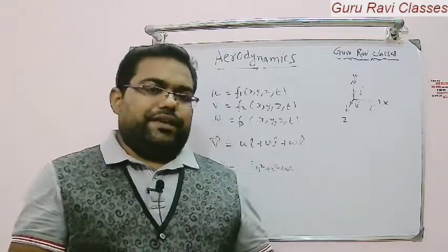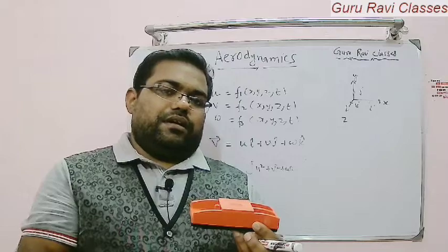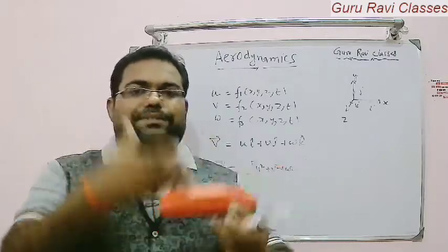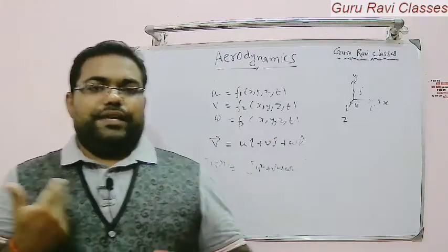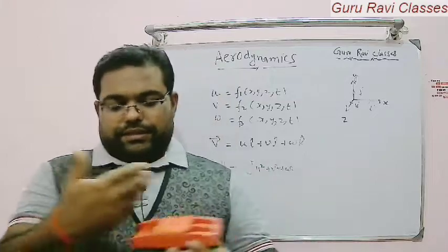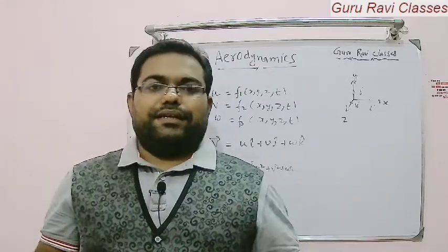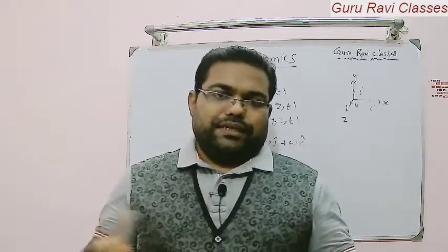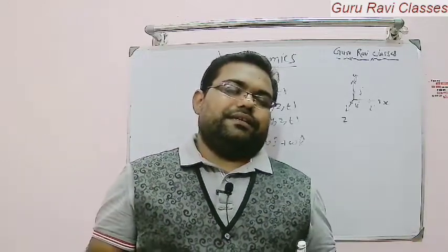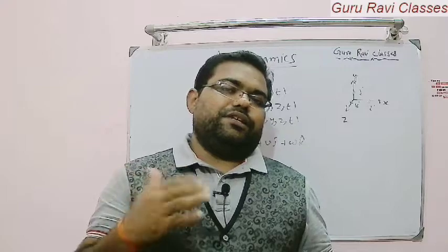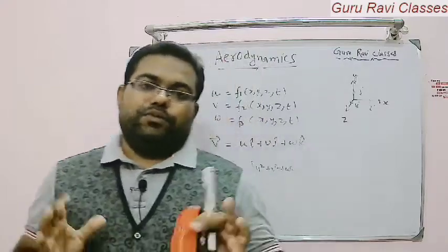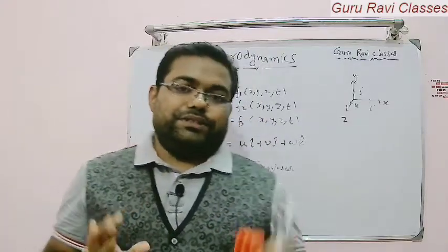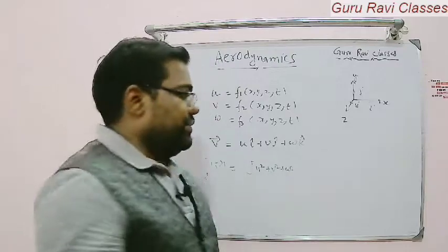If I take the pressure balance perpendicular to the flow direction, that will give the lift. If I consider the pressure difference along the flow direction, that will give the drag. If I go opposite to that, sideways, that will give the side force. So if an unbalanced potential is there, the respective force can be calculated the moment I have a clear idea about the pressure distribution. So let's go for pressure.